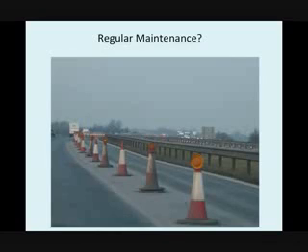Lamps should be kept clean. You can clearly see that these are dirty because the sensors in the lamps think it's actually darkness, so the lamps stay on through the daytime. And things like that, which again costs you money in the end because you've got to keep replacing the batteries a lot more often than you normally would have to. So there's knock-on effects for not maintaining your site correctly as well.